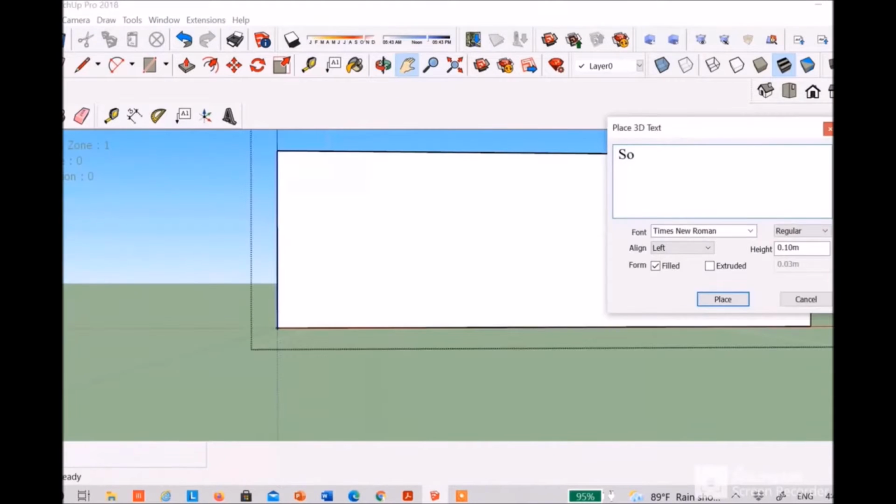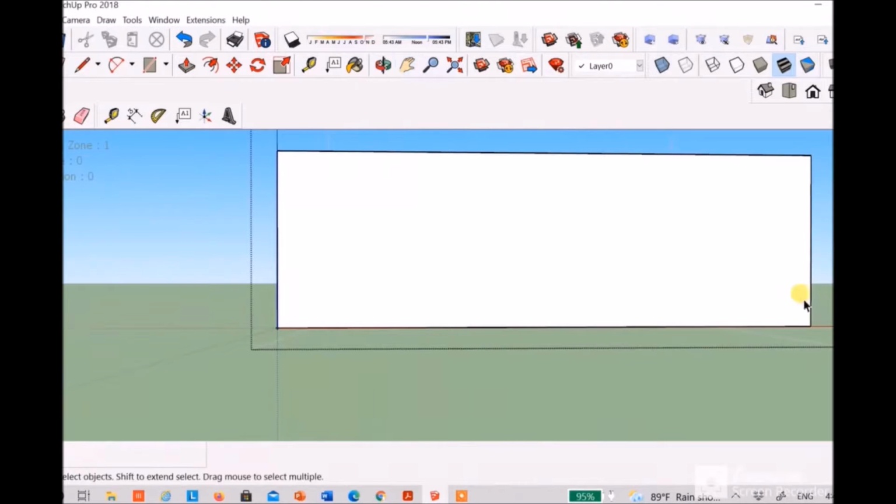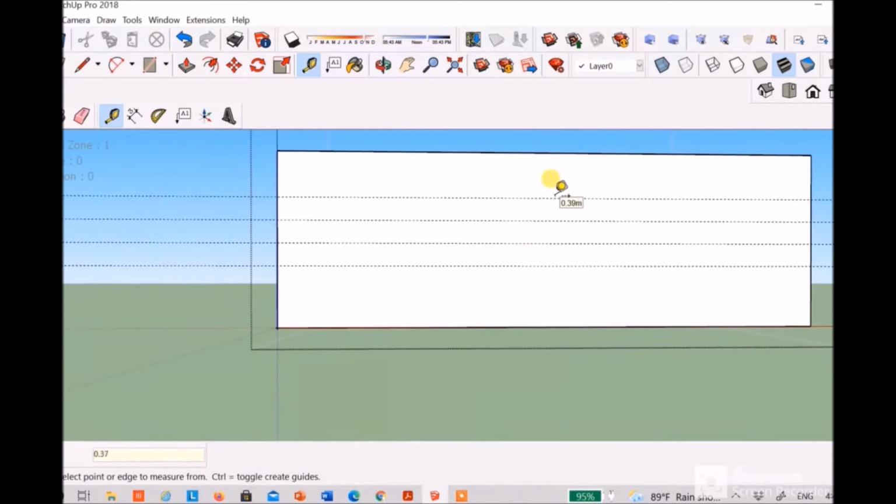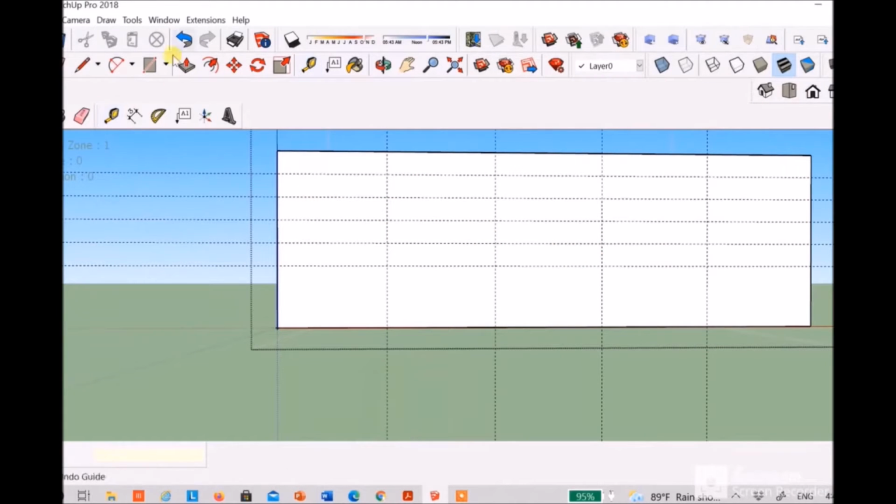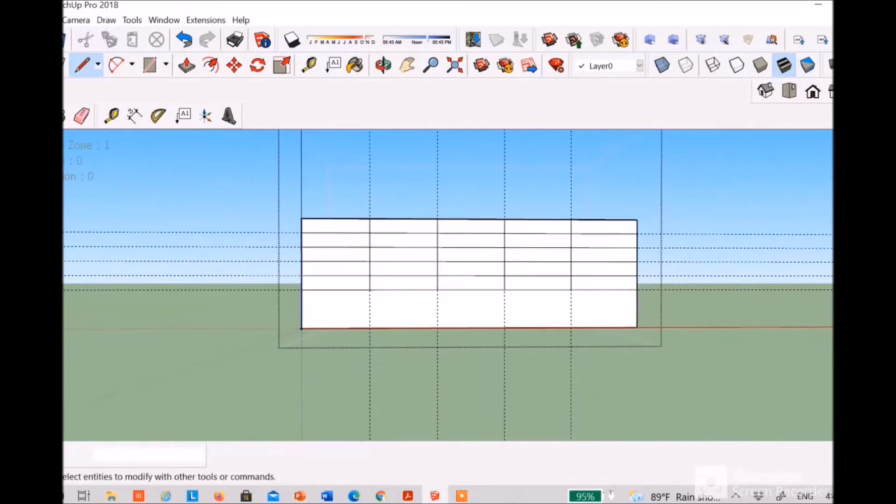This we call the south facade, which is wall 2, and which has 26 sections. Similar to before, we enter the length from floor to work plane as 1 meter and we divide the work plane to ceiling into 5 horizontal divisions of 0.37 meter and 5 vertical divisions of 1.76 meter each. We draw edges between the endpoints both horizontally and vertically, and we delete the extra lines as before.